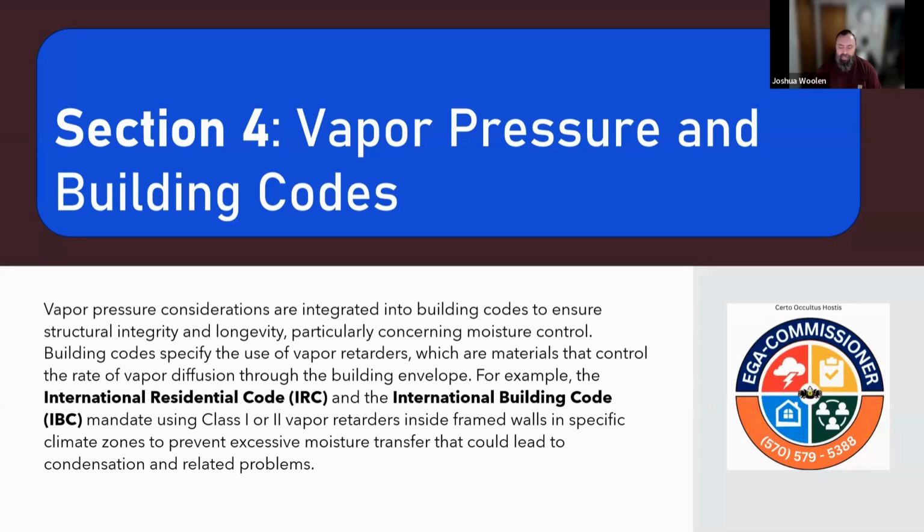They may change phases of putting the building together so that they can protect the drywall that's inside the building, or the honey board that goes on the exterior, or a wrap on the building. And here in the US, and I'm not sure about other parts of the world, we have pretty much three wall types, right? One wall, we have a wrap on the exterior of the studs, and that's typically in our summer climates, our hotter climates, because of the HVAC systems and keeping the environment from outside coming in.